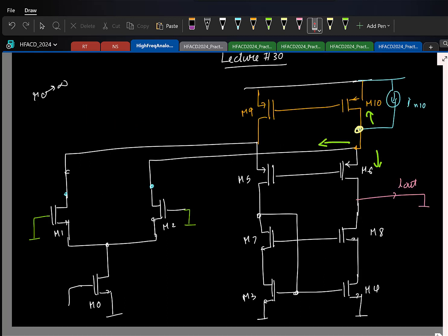And if you recollect, what is the maximum common mode we can have for the input here? No, but finally if you work out everything, it can reach as close as VDD, right? I mean, it can be equal to VDD, it can be higher also actually. Similarly, if you use a PMOS input, the common mode can be 0 at the input.